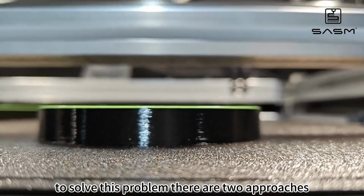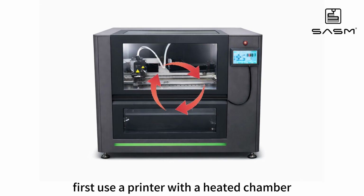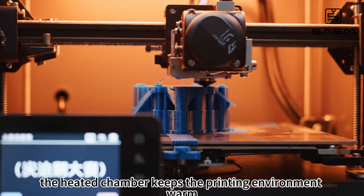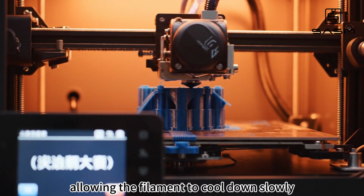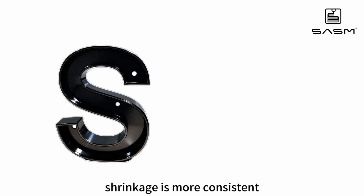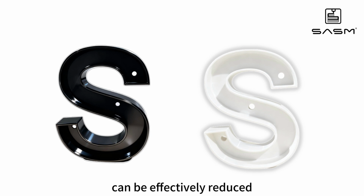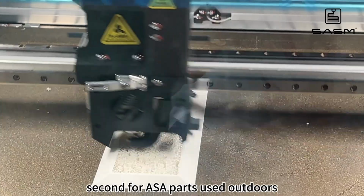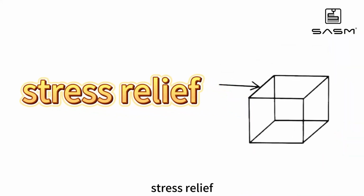To solve this problem, there are two approaches. First, use a printer with a heated chamber. The heated chamber keeps the printing environment warm, allowing the filament to cool down slowly. When cooling becomes more uniform, shrinkage is more consistent, and issues such as warping and deformation during printing can be effectively reduced. Second, for ASA parts used outdoors, there is one essential step that cannot be skipped: stress relief.